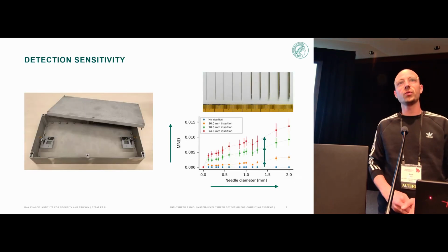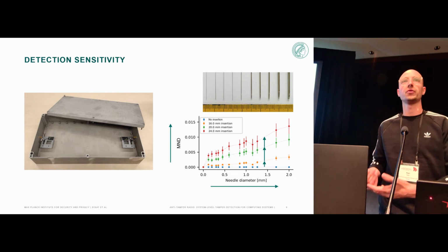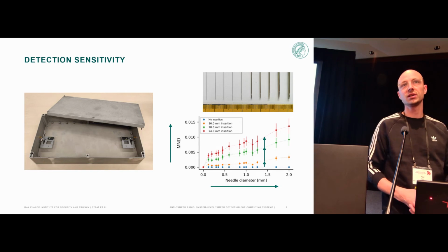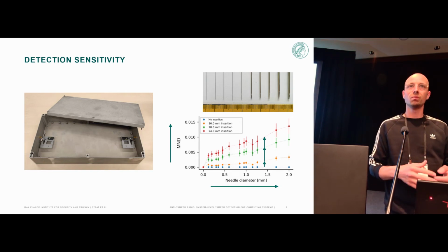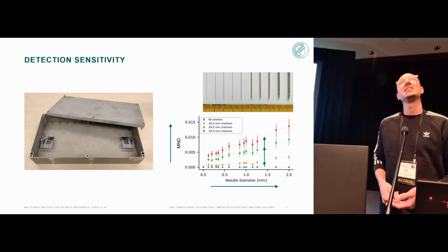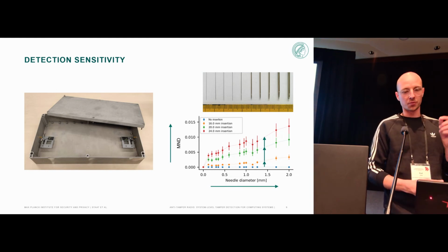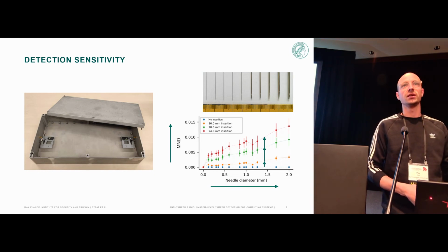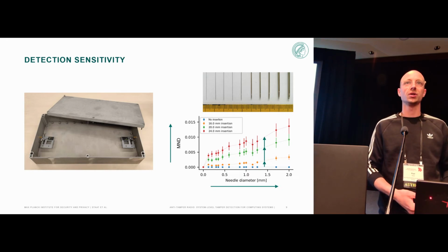In our paper, we have investigated only needles of different diameter, and only metallic needles. We are aware, and we have also discussed some cases in the paper, where the attacker could use non-metallic needles. But in the case of probing an actual connection on the PCB, a metallic needle would be required, of course,